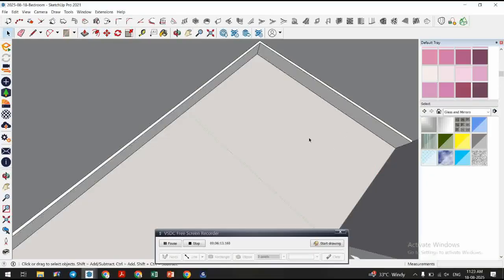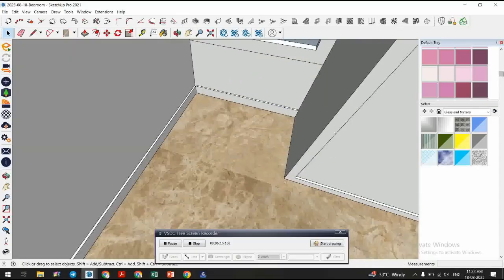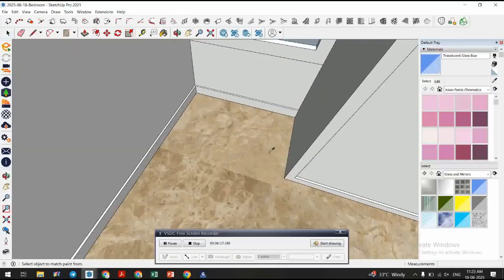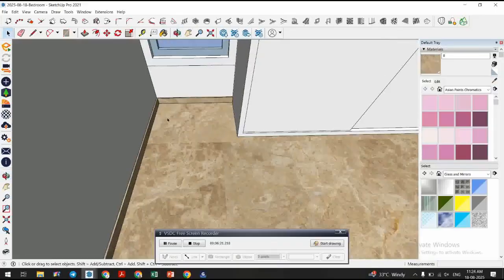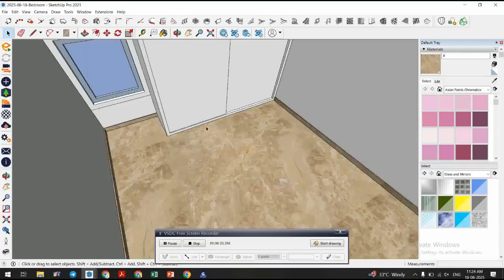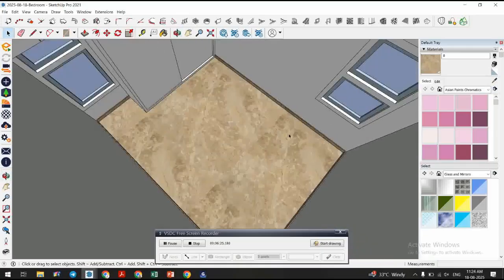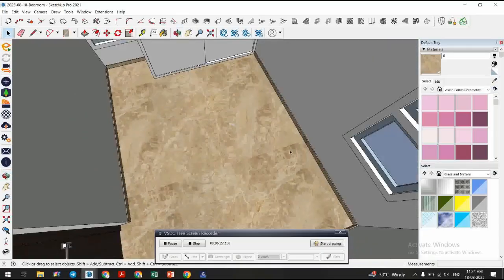So only then we will stick this skirting tile to the walls. If it is a wardrobe, we will avoid that, since for the wardrobe by default we will provide a skirting gap there. So now this gives a complete picture of your floor area.